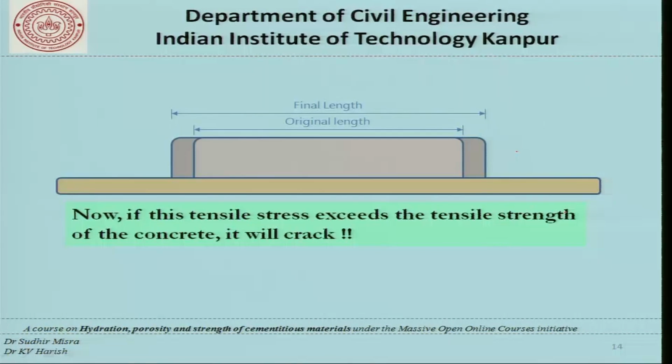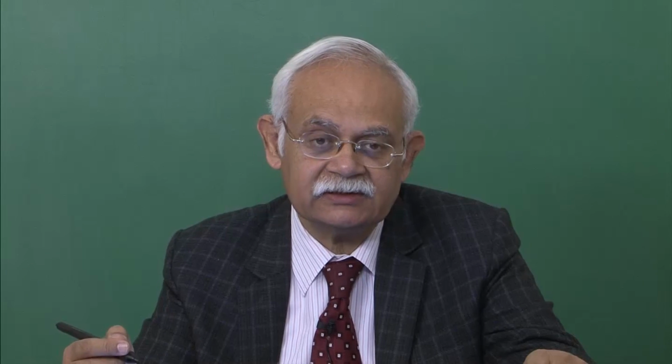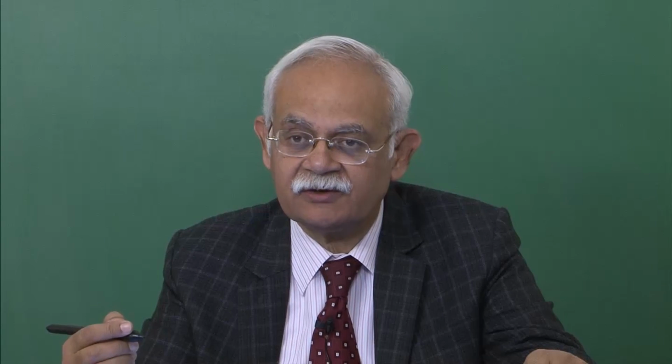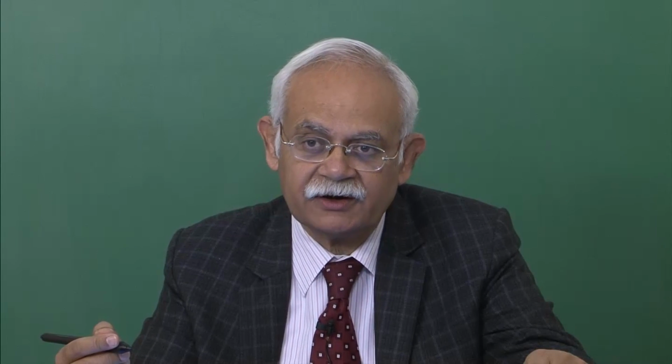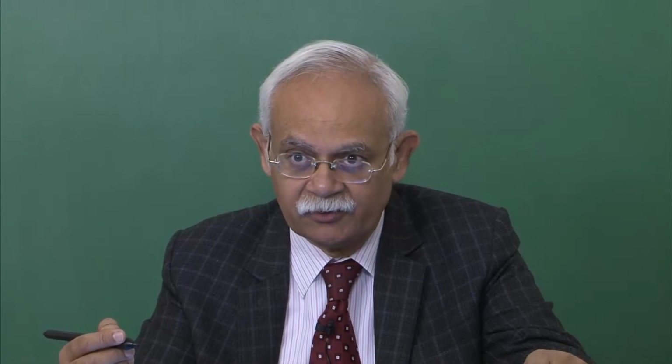And if this tensile strength is exceeded by the tensile stress, the concrete will crack. We must remember that when we are talking of this is stress and this is strength, both are actually functions of time, and therefore we must keep in mind a discussion as to how the tensile stresses develop over time and how the tensile strength develops over time. Equations and guidelines for 28-day strength of concrete, the 28-day modulus of elasticity of concrete are not really helpful.